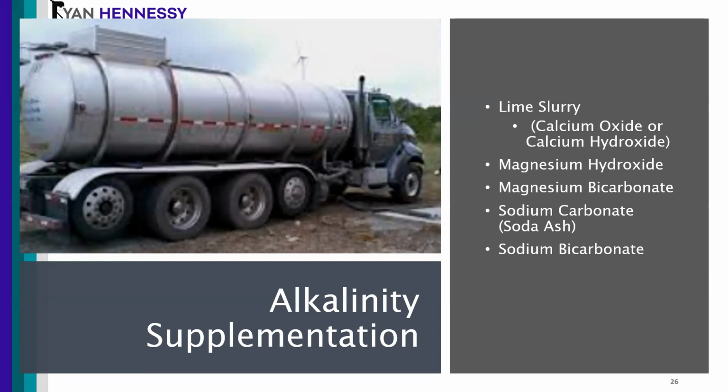So we can recover some alkalinity through denitrification, which we'll talk about in the next section of this presentation, or you can supplement alkalinity. And a lot of times the alkalinity that you have is really a function of the location and the geology of where you are. So a lot of plants in the Midwest have very high hardness and high alkalinity in the groundwater. For example, they use the groundwater for drinking water that makes its way down into the wastewater plant. And a lot of those types of plants very rarely have to add alkalinity.